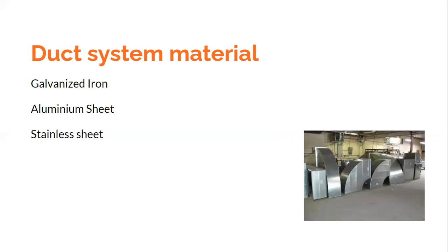So there are some trade-offs. If you want to sacrifice some comfort, we can gain on the initial cost. But if you want comfort, or if the application demands that there has to be no compromise on the duct materials, then we need to go for costlier materials like aluminum or stainless steel. Some applications, like kitchen exhaust, for example, would use heavy gauge black steel. In kitchen exhaust you would find that black steel is used, and it is of a heavy gauge. Gauge means thickness; the thickness has to be more.